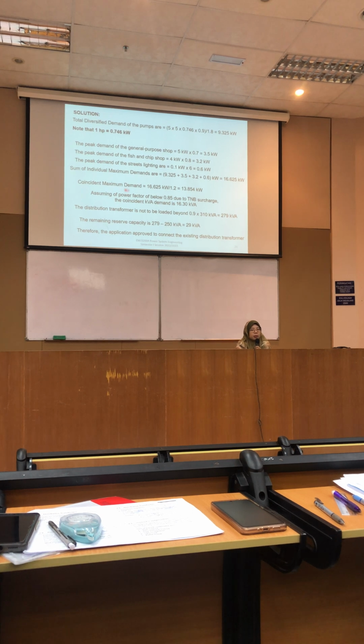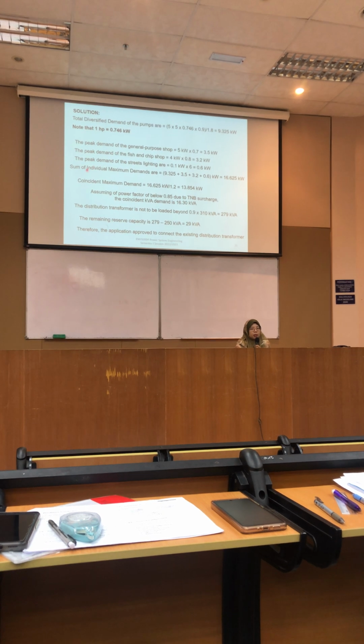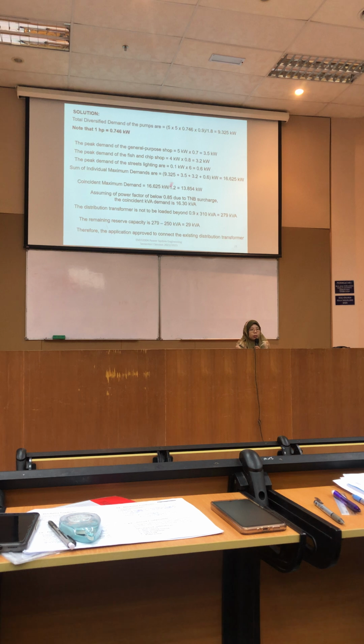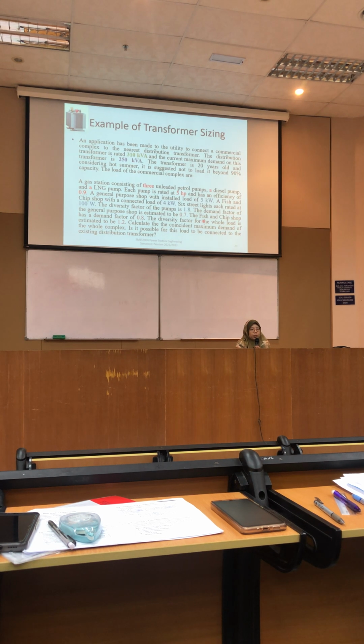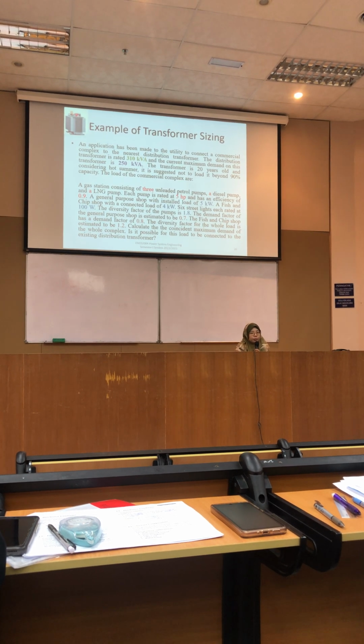And the coincident maximum demand is the individual maximum demand divided by 1.2. What is 1.2? 1.2 is the diversity factor.